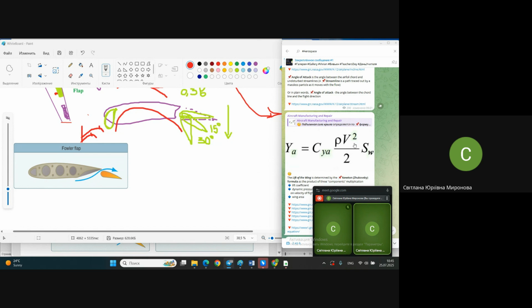And the airplane, reducing the speed like a stone, not like a stone of course, but some ballistic trajectory additionally improved by these aerodynamical surfaces, is falling down to the runway actually. It will be a very stiff landing, if not even a crash. Dangerous for passengers, for crew, for cargo, and for the airplane structure itself. Not each landing gear is able to stand such loads.